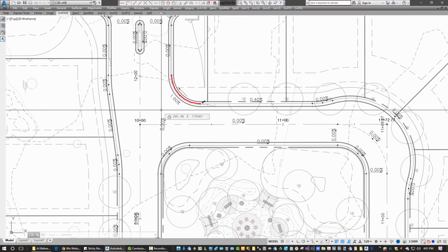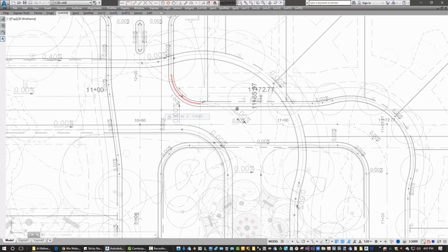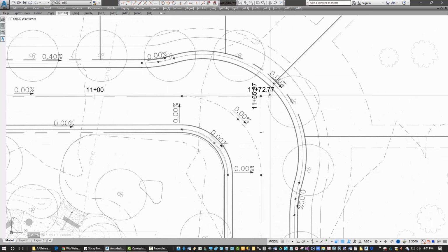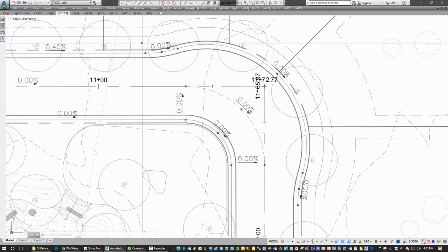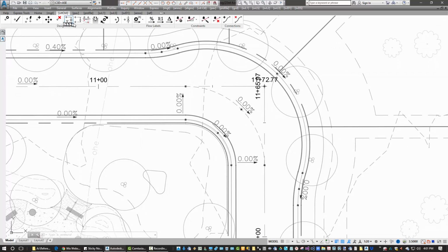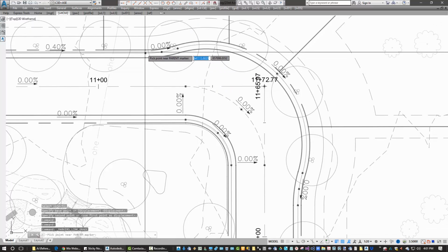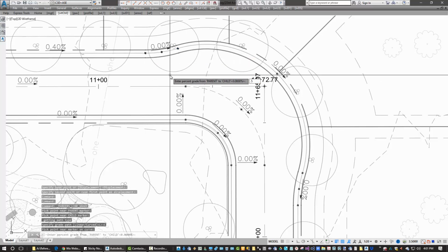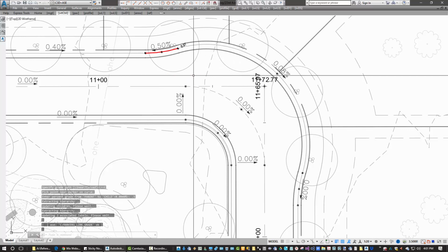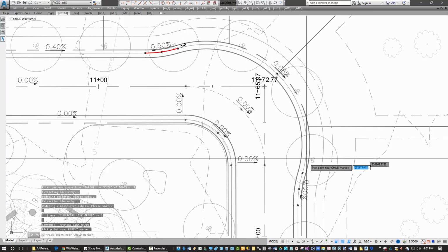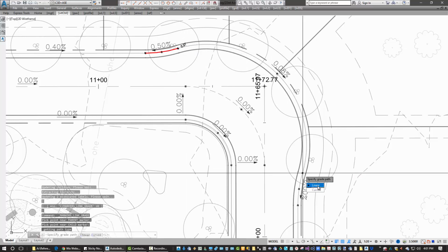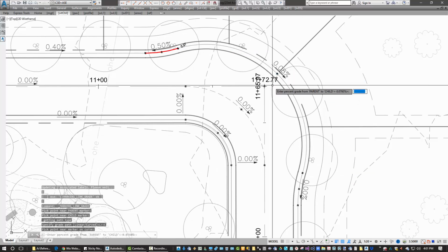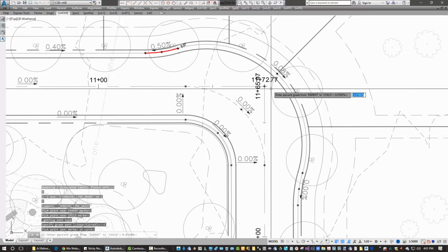So I'll go through the remainder of the site and create constraints where I think I may need them in this design. Let's say that I want to maintain a 1% grade through this knuckle just to start out with. I'll create a constraint, or 3 constraints at 0.5%. So I'll go by grade, from, to, curved, and we'll say 0.5. Repeat that. And direction is important here because the value measures from the first marker picked to the next marker picked.